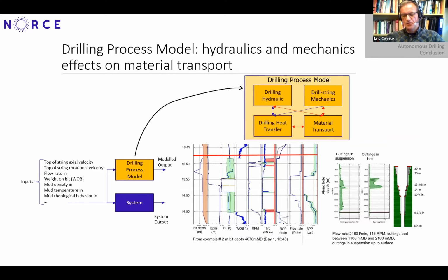And because of that, the fluid velocity was very much reduced in this very large section of the hole. And because of that, there was a cuttings bed, as calculated by our transient cuttings transport model, which settled there. And after many hours of circulation, that cuttings bed was relatively filled, and then cuttings managed to pass over the cuttings bed back to surface.